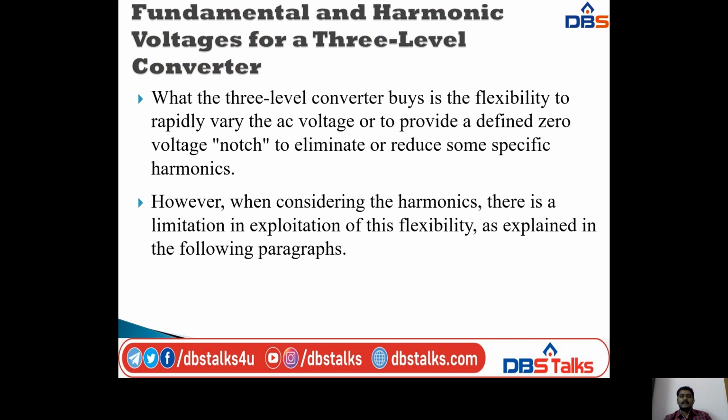Next, another concept for the three level voltage converter is fundamental and harmonic voltages for a three level converter. What the three level converter buys is the flexibility to rapidly vary the AC voltage or to provide a defined zero voltage notch to eliminate or reduce some specific harmonics. However, when considering the harmonics, there is a limitation in exploitation of this flexibility. These things will be explained using this concept.